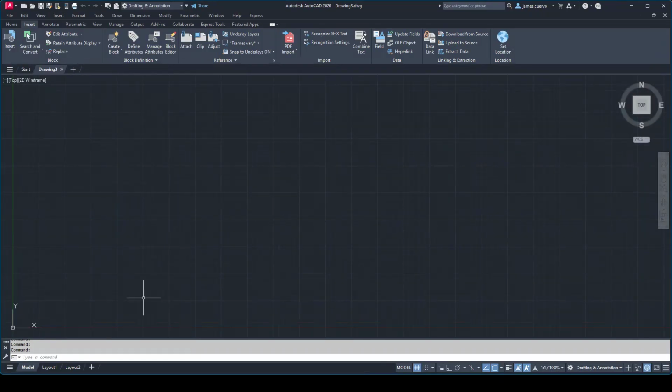So the question really becomes now, how do we switch this over to have that dialog box? Well, the first thing we need to do is invoke the startup variable, select startup, and by default it usually gives you no dialog box whatsoever. In order to get the dialog box, you need to switch it over to number one, hit the enter key, and then close this particular drawing.